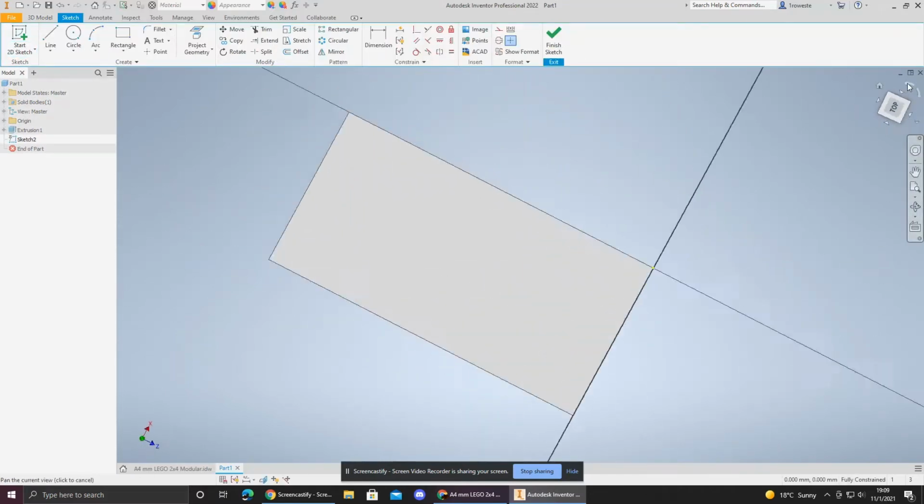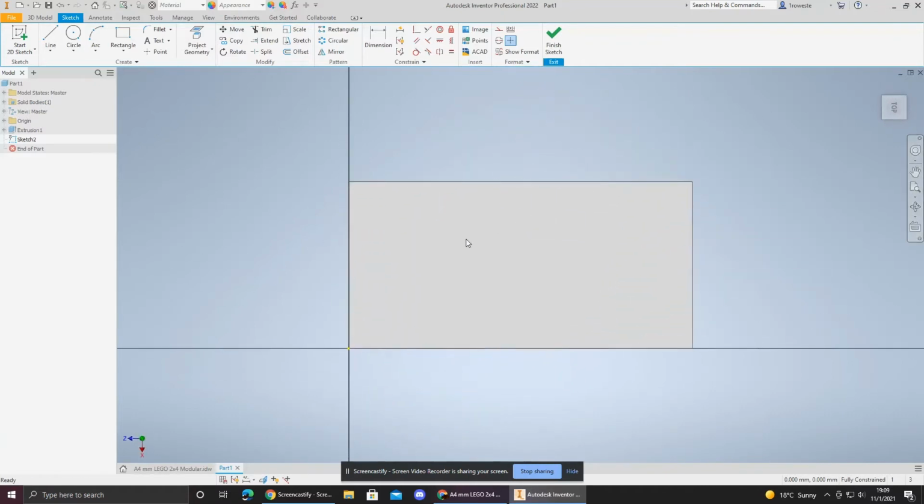After doing this, it's possible to rotate this as you like to simply get the appropriate angle, and we can place a circle on the top. Now, there are multiple ways you could go about doing this. You could, if you wanted to, although this is bad practice, simply go in 4 millimeters, 4 millimeters. Oh, see, that didn't work. Bad practice. But you could go in 4 millimeters and 4 millimeters, and then place your circle's center point on that and create the appropriate 4.8 millimeter diameter circle at that point.